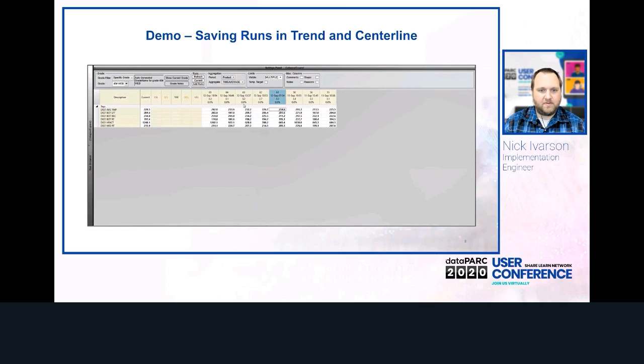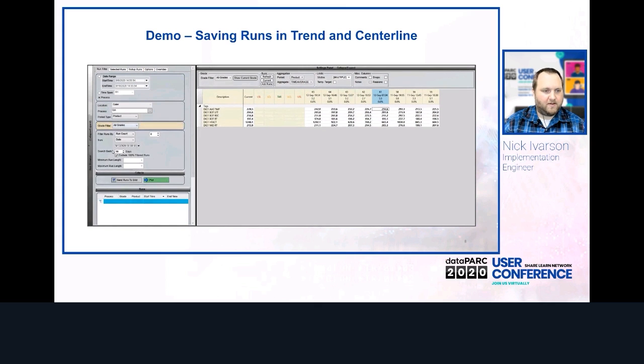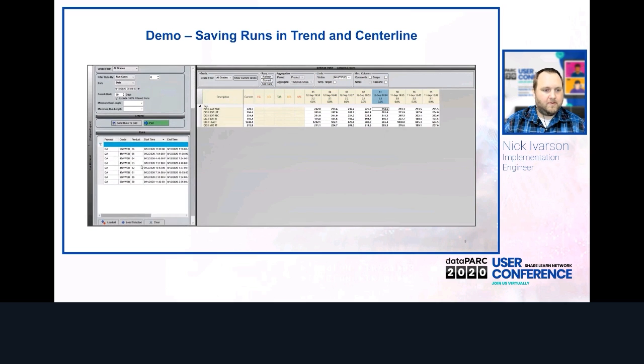Now in run browser, I have essentially the same things that are pulled back. So see that run number 63, it's third from the left. And then I'll use the run browser. It's in the charts, it's over on the left as a tab, a little ribbon kind of thing. This is largely the same. Let's make sure I've got the same settings here. It's all grades, yeah, all grades, we need to change that too. But same settings as before. And so now I'll send runs to the grid. You'll see that button's in a little bit different place. But from here on, the same procedure.